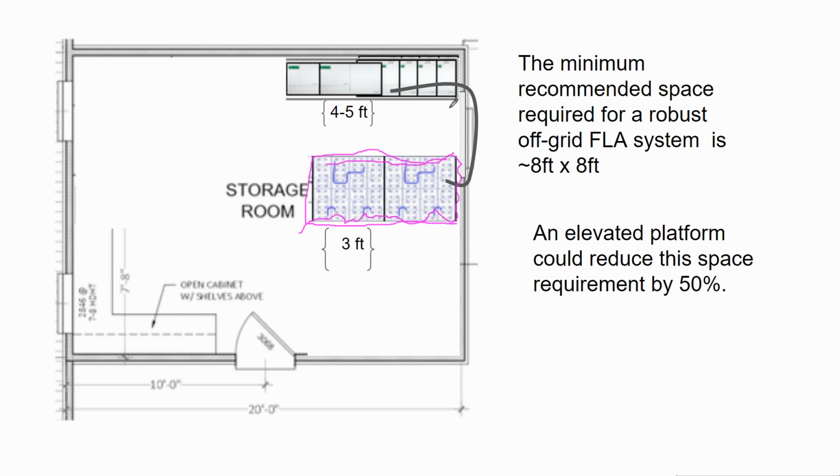But then keep your batteries and your inverters about 4 to 5 feet away from each other, so that you don't have to add the additional disconnect, but also that you have the 3.5 feet to 4 feet of working space between your inverters and your batteries. Possibly, if your charge controller and your inverter and service panel are small enough, another good place to locate them would be right on the end right here on their own rack, kind of facing outwards.